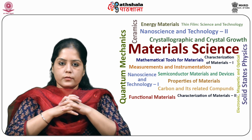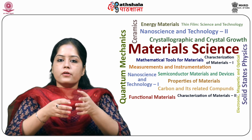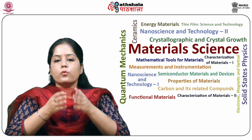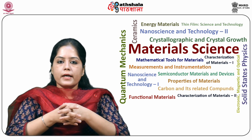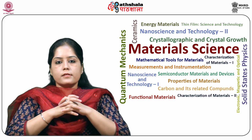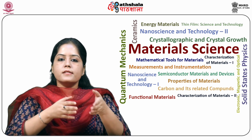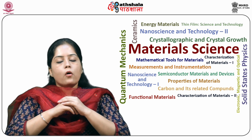transistors, JFET. The field effect transistors come in several forms. In a junction FET, called JFET, the control gate voltage varies the depletion width of a reverse biased PN junction. A similar device results if the junction is replaced by a Schottky barrier, that is metal semiconductor FET, called MESFET.